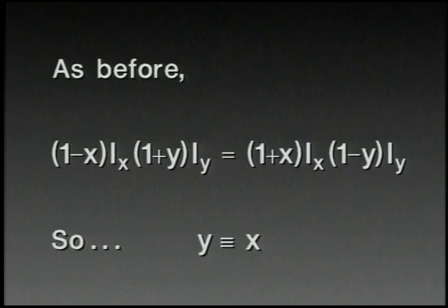First, let's analyze that using the translinear principle as before. And once again, we find that given that all the junctions have the same emitter area, or that the emitter areas are adjusted so that the area factor is still unity, then the output modulation index Y is identical to the input modulation index X.